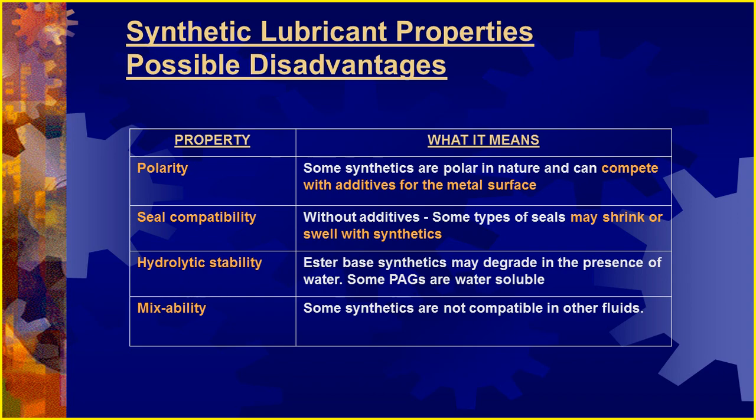The other situations you have to look at are polarity, seal capability, and other stabilities that are in here. In other words, for the polarity, its ability to draw in, this is why you need esters with your synthetics. Seal capability: because there are so many solvents in it, against a rubber type seal, you have to have what's called a butyl or other type seals that are designed for synthetics. You put a synthetic in an old car, it's going to be very destructive, because back then they didn't have synthetics, they just had more of your Group 1 and Group 2 oils. So make sure you've got the right oil for the right design.